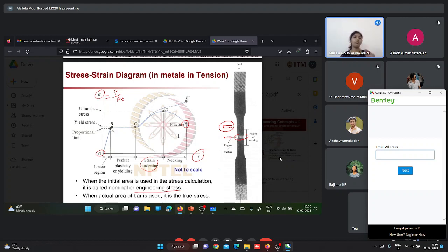If you combine both cement and steel, then you can take care of both compression and tension. When the concrete has to take the compression loading, it will be able to take care of it. But when it has to take the tensile load, it will not be able to. That's why if you incorporate steel in the tension region of concrete, it will take care of the tensile stresses which are going to come onto the material. So this is the fracture point.